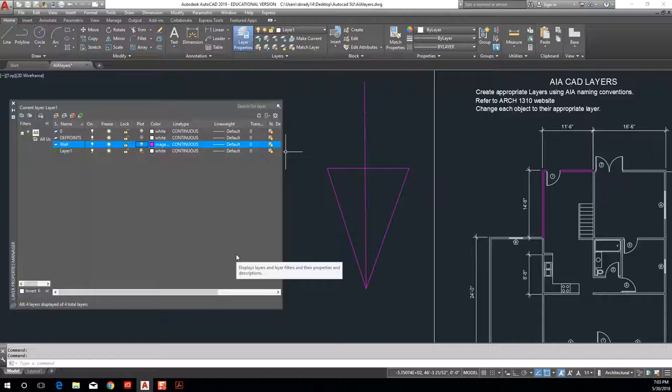So that when you're in a rush and you have a deadline and you're going to print your drawings, you're like, oh, I can see the furniture, it's there, and you go and print hundreds of copies of drawings that cost $4,000 and nothing is printing. You're like, oh, well, it was on the screen, right? So I'm more likely to freeze and thaw things if I don't want to show a client, more so than making them non-printable, so that you don't mistakenly create PDFs or drawings with things missing, essentially.